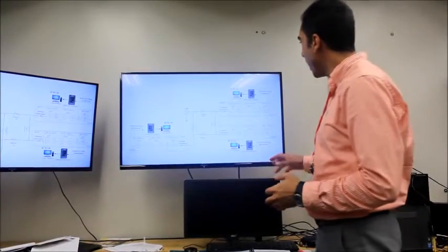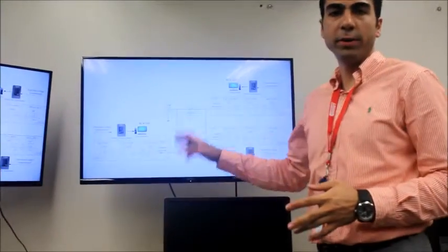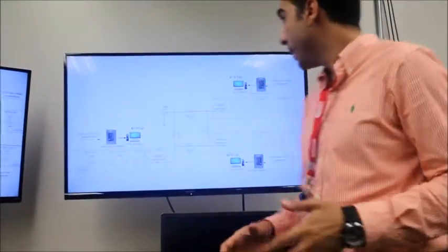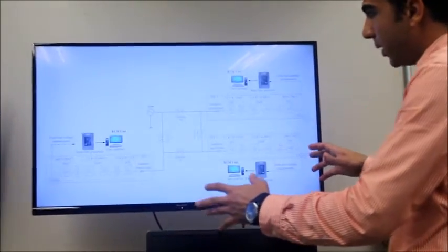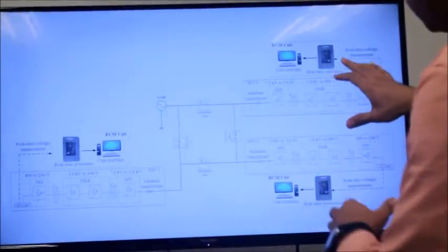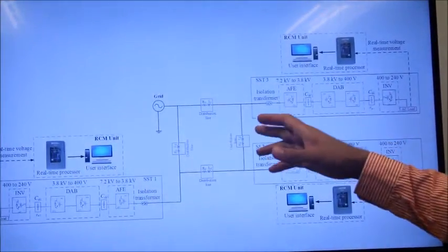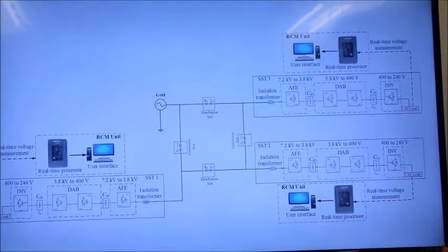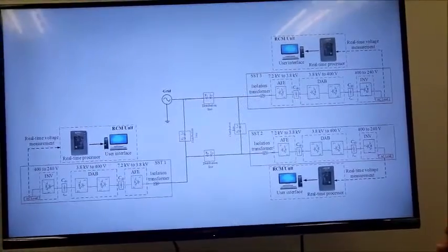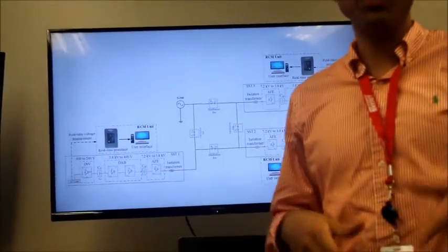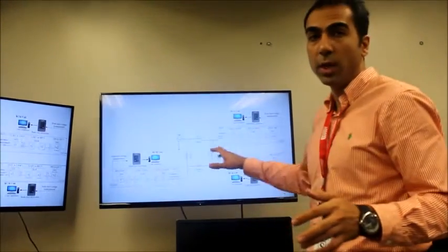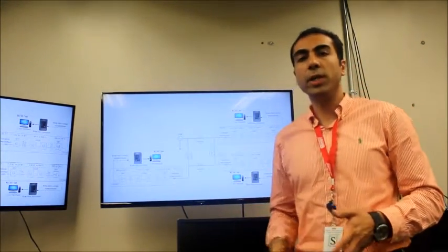In this experiment, we have connected 3 real-time processors. We have 3 myRIO processors from National Instruments. As you can see from this picture, 3 SSTs are all connected to the processors, and processors are connected to the LabVIEW interface. So we can see the result in real time in LabVIEW. Okay. So we have already imported the data in the hard drive in the real-time processors, and processors are connected to the SST. What we measure here is the voltage at the load side.